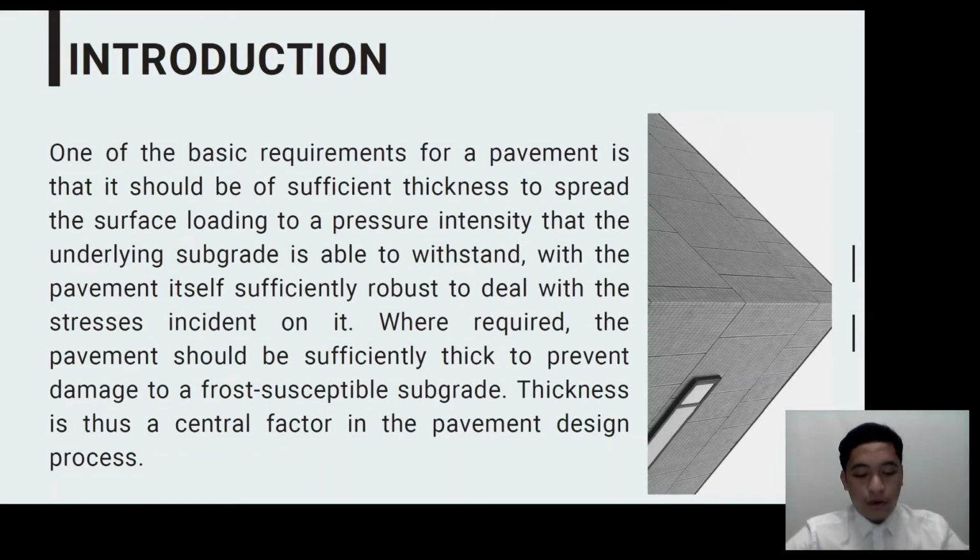One of the basic requirements of pavements is that it should be of sufficient thickness to spread the surface loading to a pressure intensity that is tolerable to the underlying subgrade, and also be sufficiently robust to deal with the stresses incident on it.